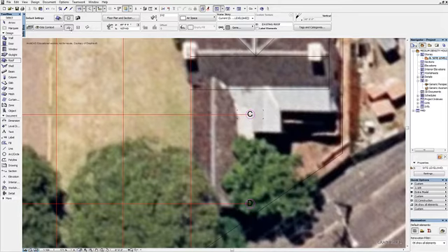It's all very well and good to try and draw this shape, as in this pointed end of the roof plane, but it's really making work a lot more difficult for us, because then we'd need to mathematically calculate the height of this ridge and at what point this would meet the existing roof plane that has already been drawn. So we're going to make life easier for ourselves by constructing with a rectangular geometry and then using a different ArchiCAD function to fix this end part of the roof.